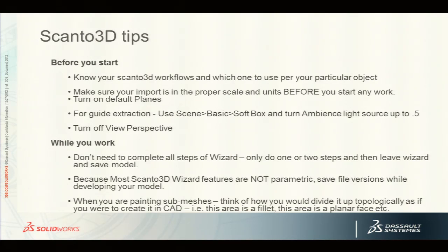And then remember, like I said before, don't feel like you have to go through every step of the wizard and complete your job in one pass. You can do parts of the wizard and just exit, save your file, and then go back. Oftentimes, before I even align the point cloud, I'll just mesh it, exit the wizard, save the file, and then go right back in again and align it. You think you have to step through every step of the wizard. You don't. You can do individual parts of the wizard. Okay?